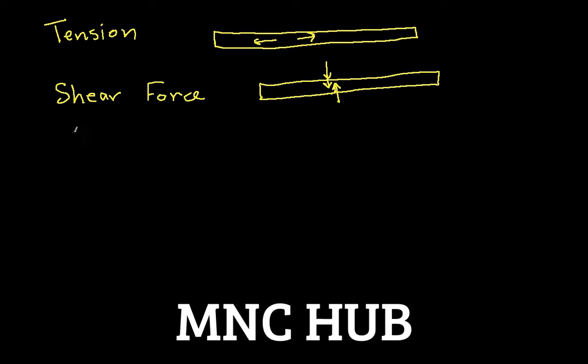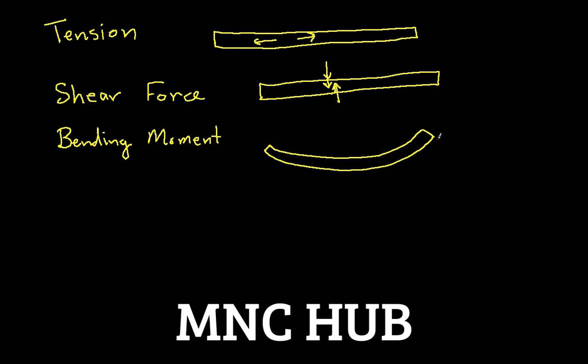to shear force. Bending moments, and the idea here is that these are moments that cause bending. So if I have a beam that should be straight and ends up looking like this because maybe, I don't know, I've dropped a very large box on it or something like that, this box is applying a moment which causes the beam to bend. Okay, so it's causing this end on the right to curl up and this end on the left to curl up.